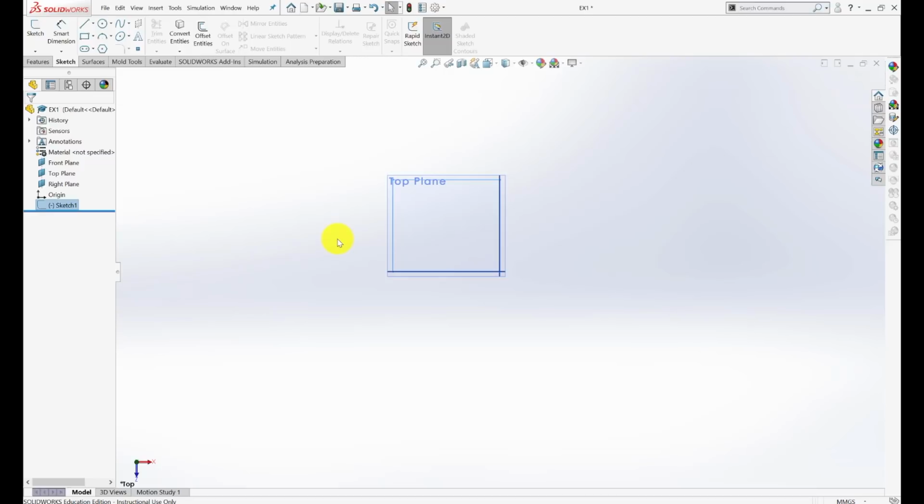I'm looking at it from the top view. That's the one that I just drew. But if I want to see this in another view, the way that I need to do this is click the center mouse button, hold it down, and rotate. Not rotate, just move side to side, pan, or whatever, and my parts will rotate all around.